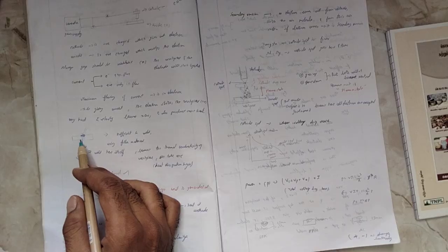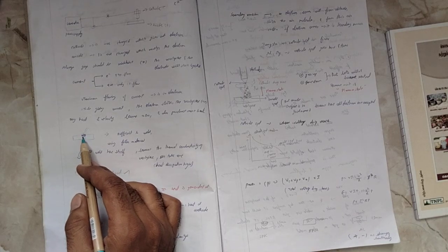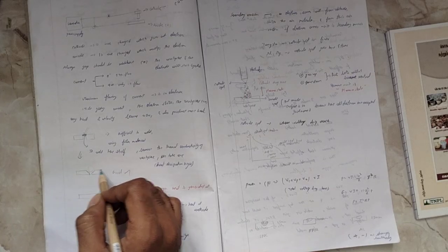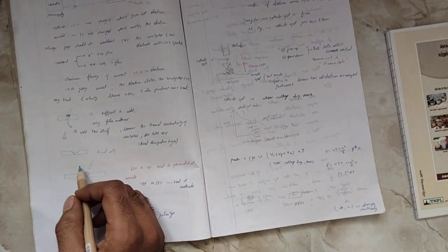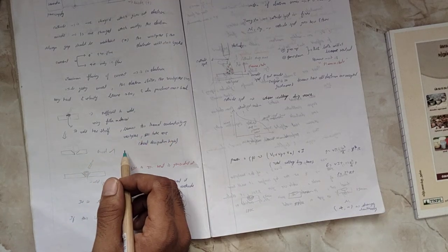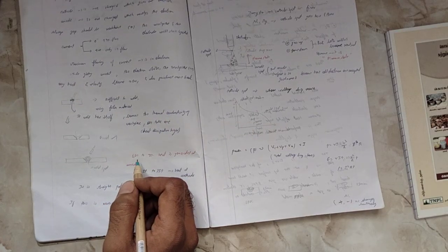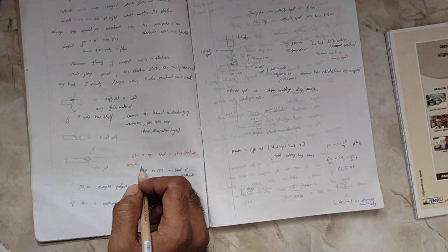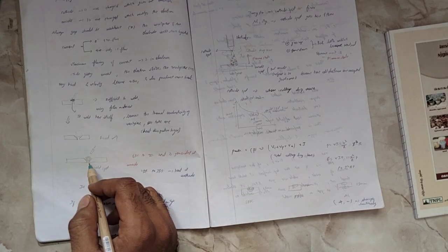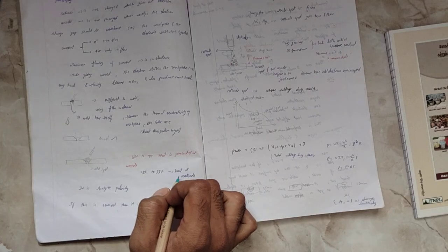And you can see, if it's like this, the welding material won't go downwards. So we take it like this and we place the welding material. So now the welding will go strong. It will go down well because, you can see, the thermal conductivity of the workpiece is so high that heat dissipation occurs more. Okay, you can see only 65% to 70% of the heat is generated at the anode level. So it means 65 to 70% of the heat is transferred, and the remaining 25% to 35% of the heat is at the cathode.